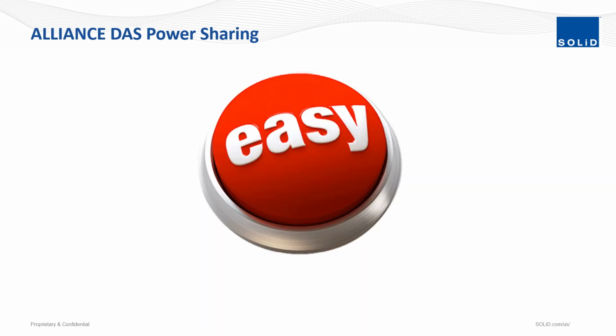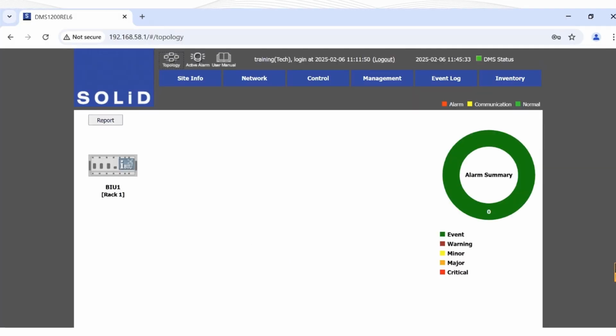EasySet is a function built into the Alliance DAS management system, the DMS 1200. It allows certified individuals to make batch changes to the DAS settings. For this video, we'll be focusing on the power distribution settings specifically. When you first log on to a DMS 1200, the topology page will come up. Before using EasySet, we will need to ensure that all MDBU ports that need to be set are activated.